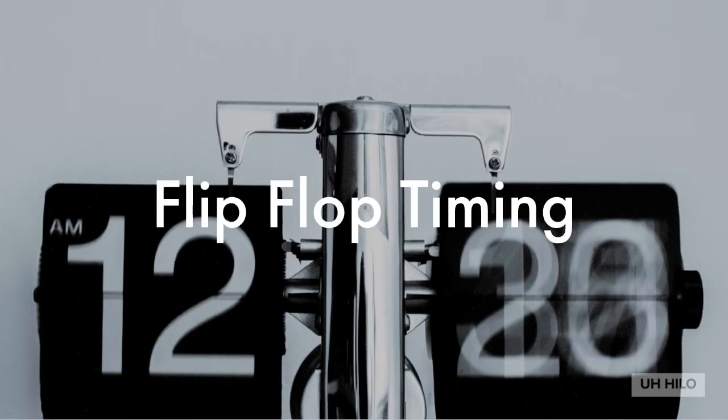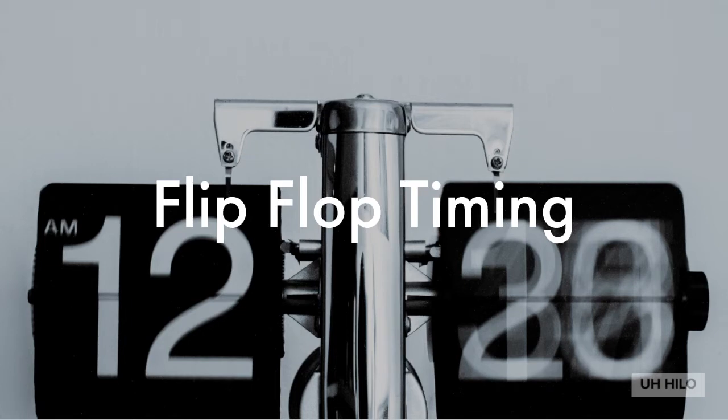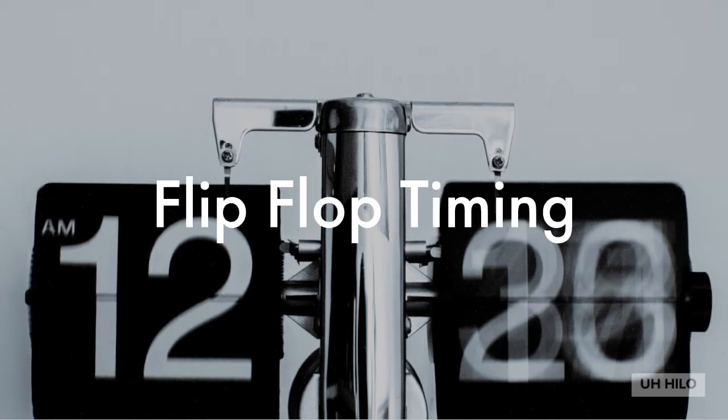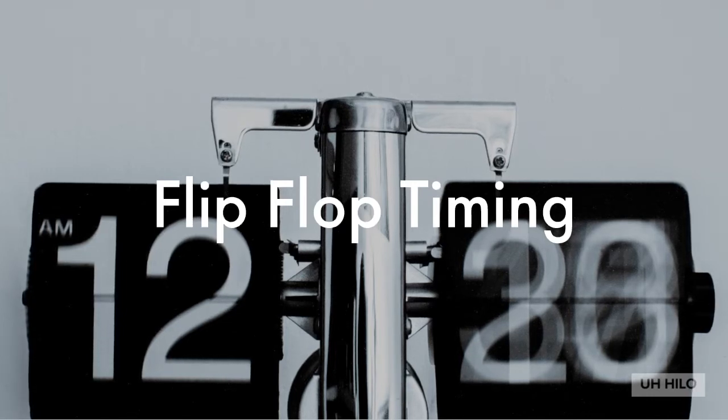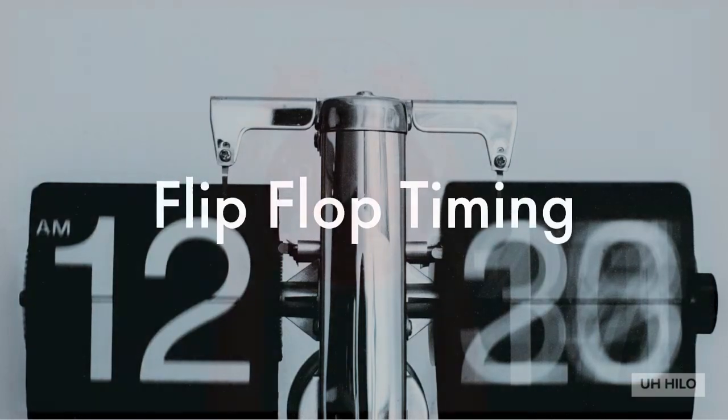The propagation delay times of the flip-flops are defined as the interval between the triggering clock edge and the stabilization of the output to a new value. Since the changes of the flip-flop outputs are to be separated from the control by the flip-flop inputs, the minimum propagation delay time should be no longer than the hold time for correct operation. You can find these parameters in the manufacturer's data books for specific integrated circuit products.